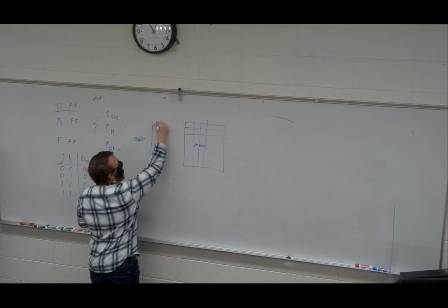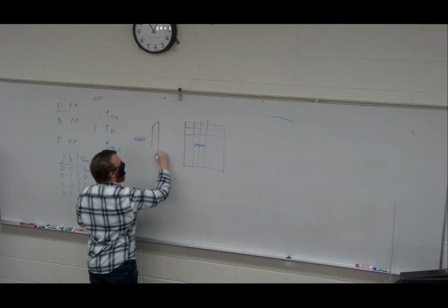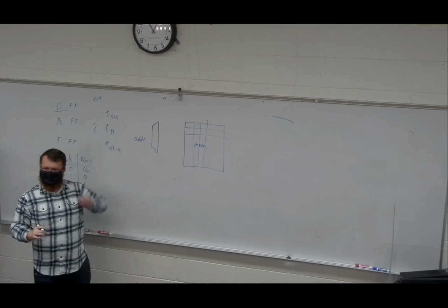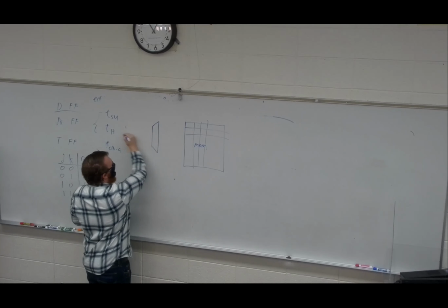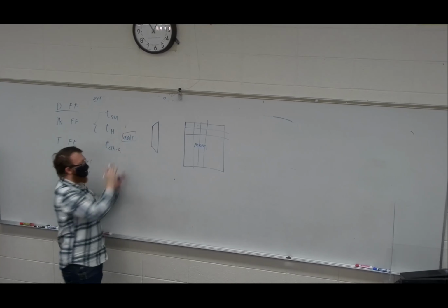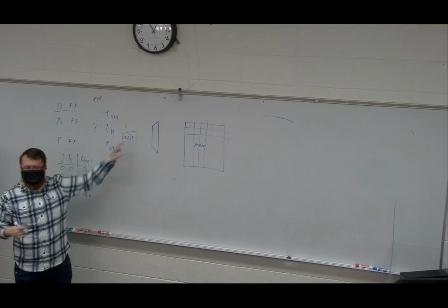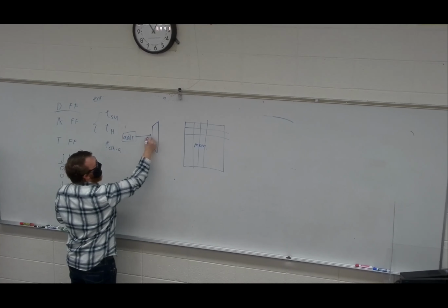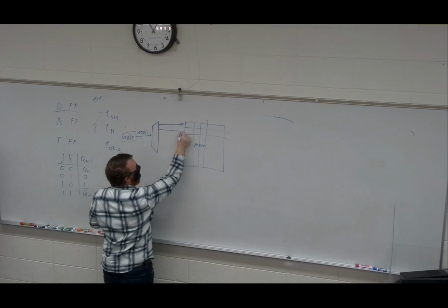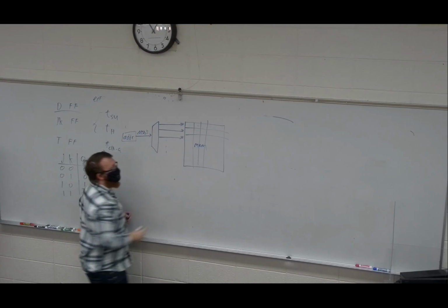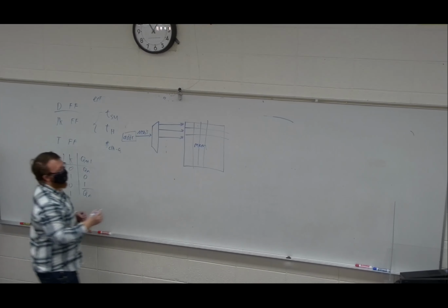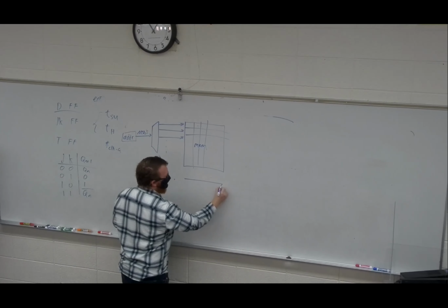One way of doing this is I feed the address into this decoder. And actually, I'm going to back off a little bit. I take the address, and this is stored in some register, and it's going to send its most significant bits off to the rows of this memory. Similarly, we're going to have a column decoder.